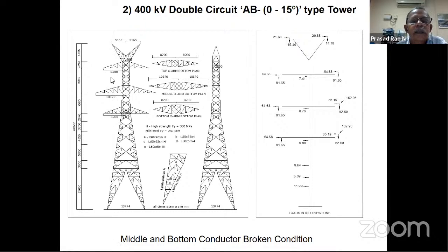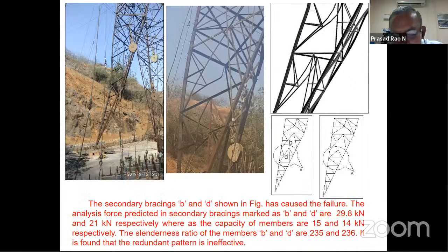You can see the typical secondary bracing failure in the second figure, where the secondary bracing is subjected to more than 2.5% and nearing an L/R of 250. So the L/R 250 limitation alone will not work. You have to check the bracings for the force in that member and the axial stiffness of the main member.